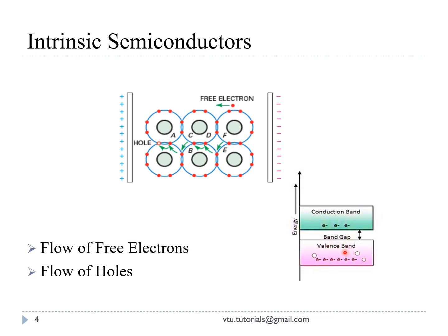When you consider here, there is a hole, the empty place. An electron jumps from the covalent bond at point B, or at A, and moves into this hole. A hole is generated at point A, and next this hole at A will be filled by one more electron, maybe from point B, and when it jumps into A, a hole results at point B.